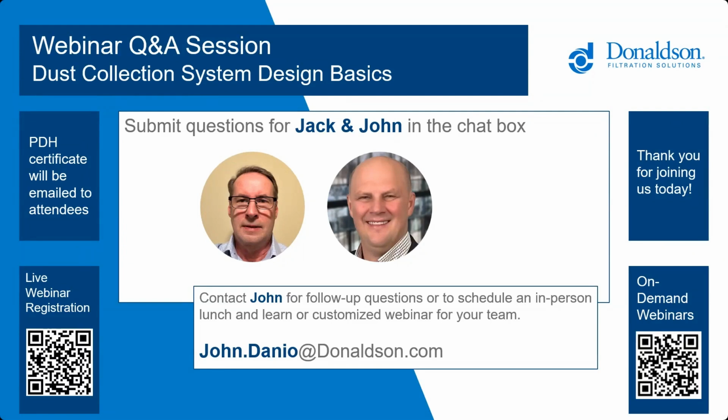Okay, so the person asking about wood shop applications, we can also reach out and get more information to you as well. So when you said PVC piping, would you really just recommend it for mist, if anything, Jack? I wouldn't recommend it at all. Okay, all right. Because again, you have tight elbows. It's designed for fluid, not really air. And we do get that question a lot, so I'm glad that someone asked that.